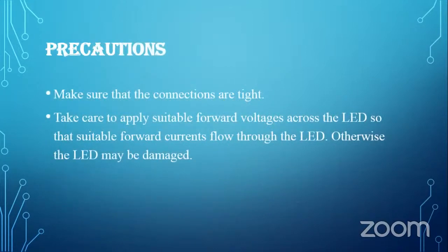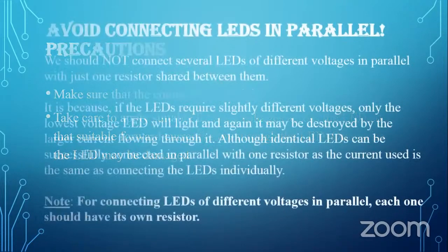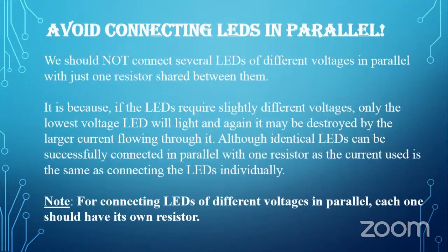Here are some precautions which are to be considered while performing this experiment. First, make sure that the connections are tight. Second, take care to apply suitable forward voltages across the LED to avoid any damage to the LED. Now, one more precaution should be considered.